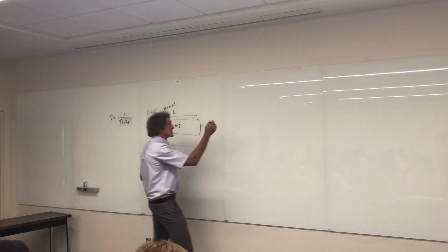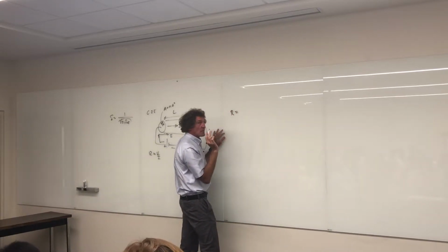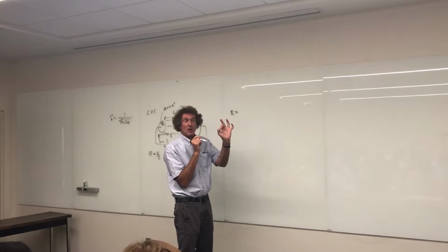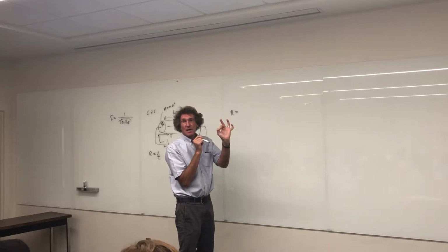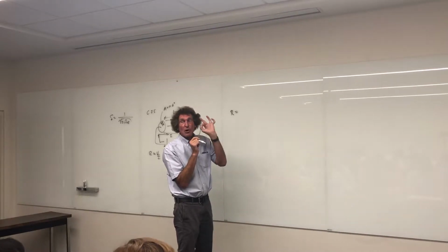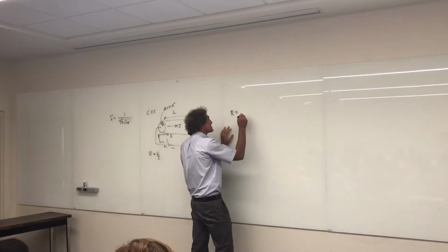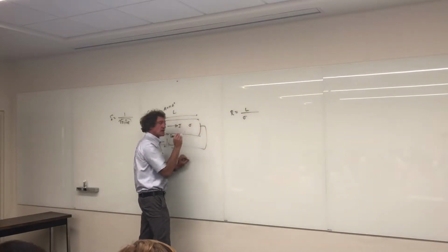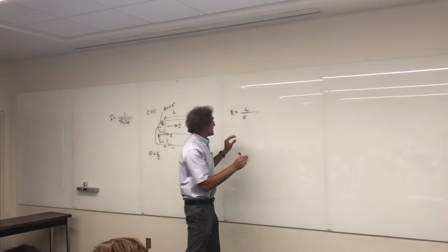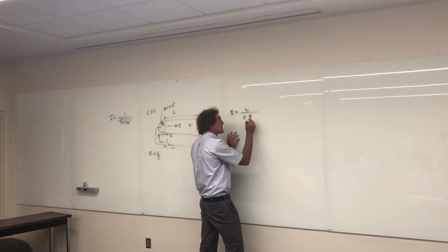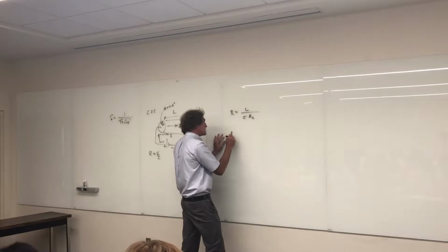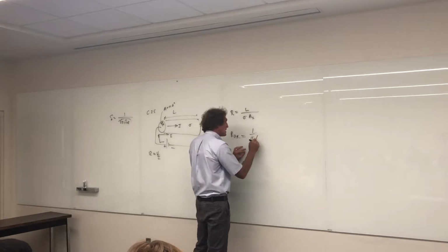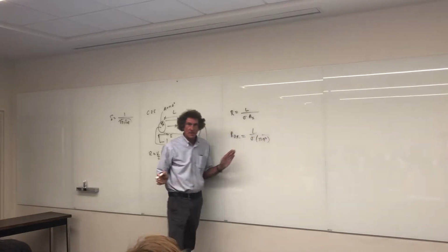When we talk about resistance down a pipe with a constant cross section, it could be rectangular, triangular, or cylindrical. As long as the cross section doesn't change, resistance is the length L divided by sigma, the conductivity of the wire, times the area that the current flows in. Now, R DC, if it's not time varying, would be L over sigma times the area, which is pi A squared. Does everybody agree with that?